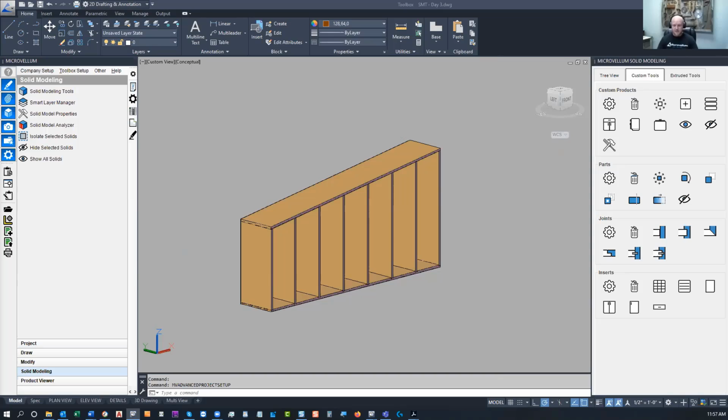that are feeding down into the formulas of the subassembly that don't exist. Another thing I've done is I've gone into a product starter and just copied all the prompts from that and dumped it in so that they exist, define my names, and then you won't run into as many limitations when inserting those sub-assemblies. So, a couple ways you can get to that, Rod.